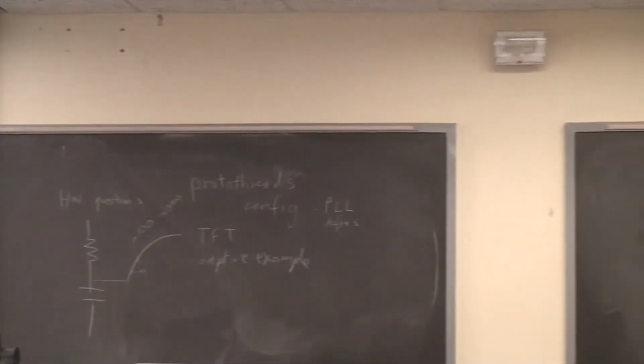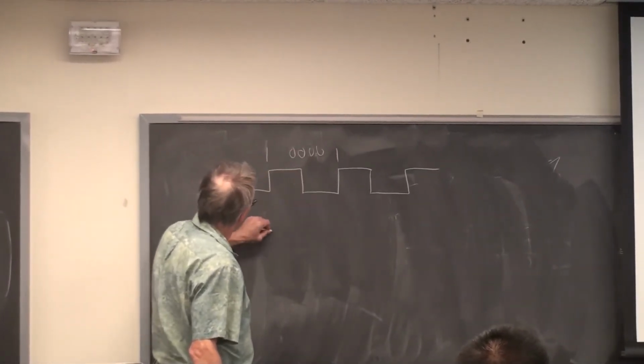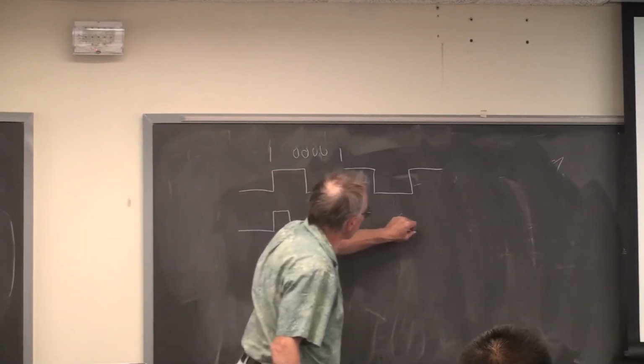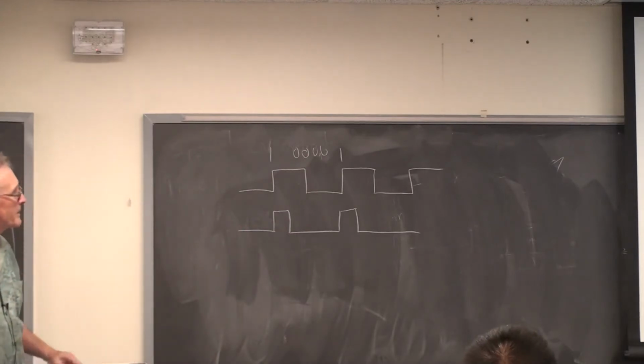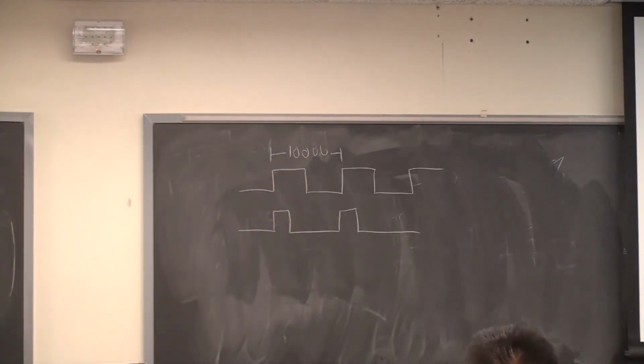So I'm going to set this up so I get a 50% duty cycle square wave at precisely 10,000 machine cycles and a 1/4 duty cycle wave at the same frequency at 10,000 machine cycles. I'll put those on pins 14 and 18. Take those two outputs and feed them back into the input capture, which is what you're going to have to use to measure the capacitance rise time. But I'm using it to measure the output of a square wave generated by the system itself. And then we're going to display the capture time on the TFT LCD.